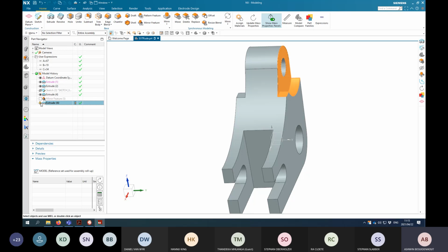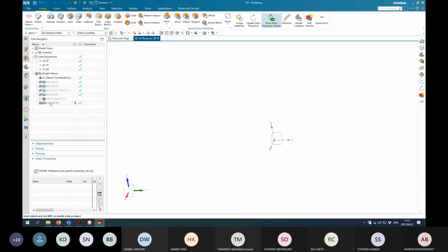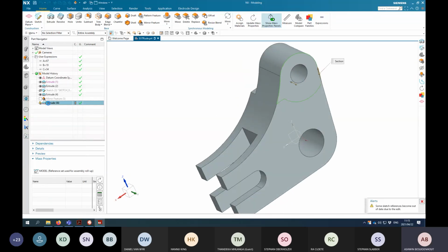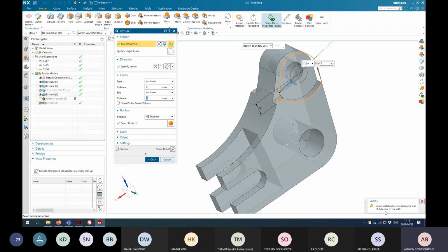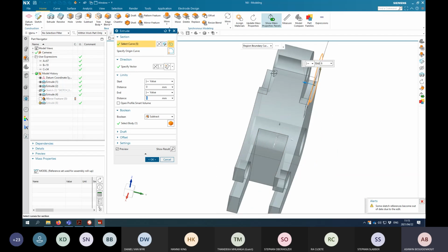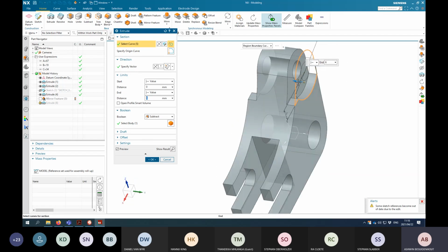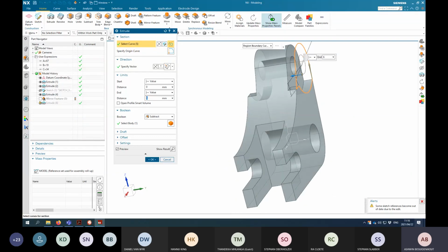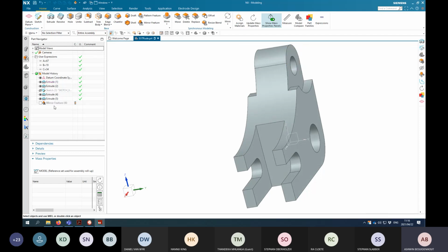Okay, so there's an error. It's an error in the extrude. See what's causing the error. Some sketch references become out of date. Okay, so it has to do with the references because this extrude is making nonsense. Yeah. So we'll see the reference. The reference is moved due to a previous edit. Oh, yeah. Let's see.